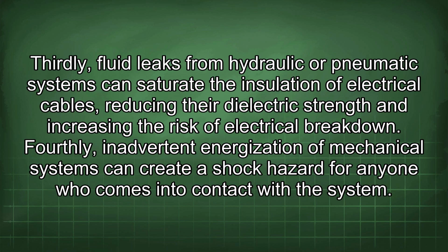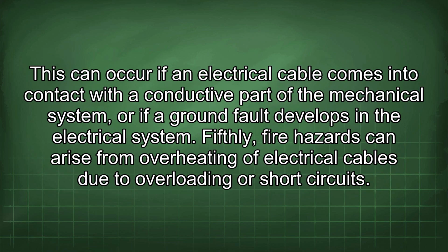Thirdly, fluid leaks from hydraulic or pneumatic systems can saturate the insulation of electrical cables, reducing their dielectric strength and increasing the risk of electrical breakdown. Fourthly, inadvertent energization of mechanical systems can create a shock hazard for anyone who comes into contact with the system. This can occur if an electrical cable comes into contact with a conductive part of the mechanical system, or if a ground fault develops in the electrical system.